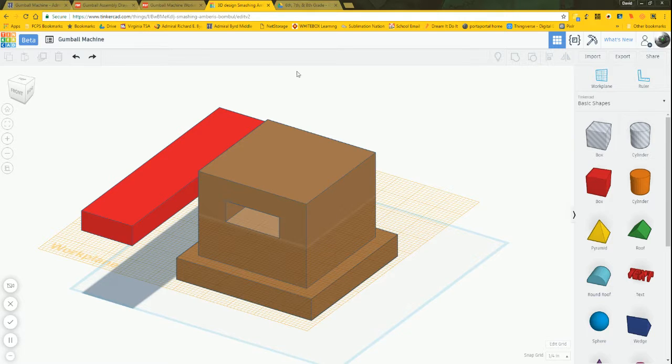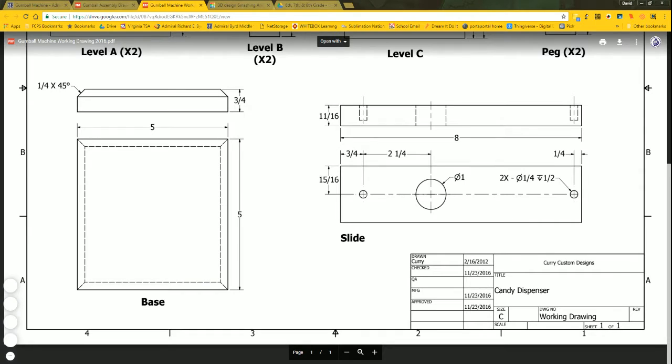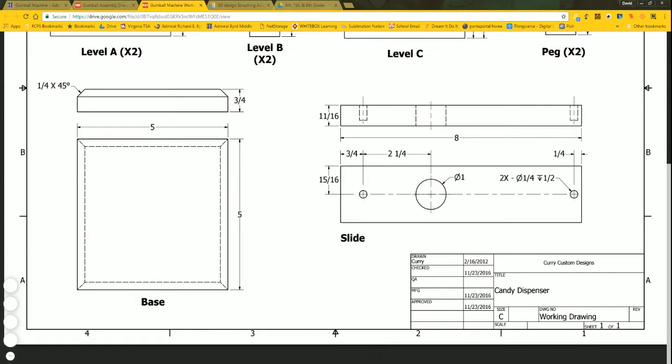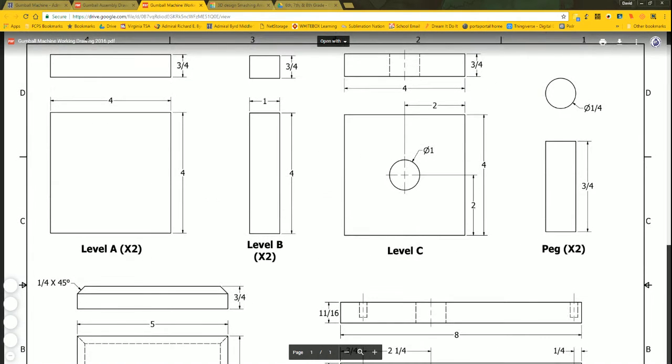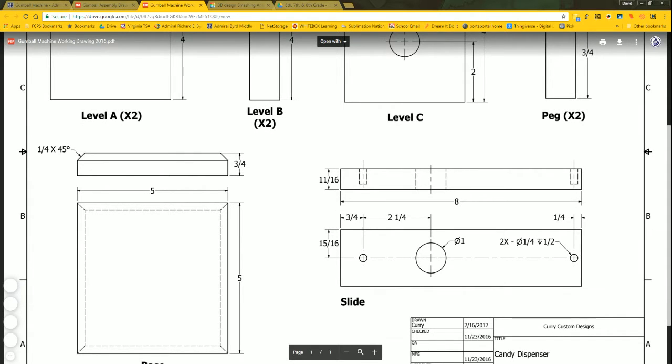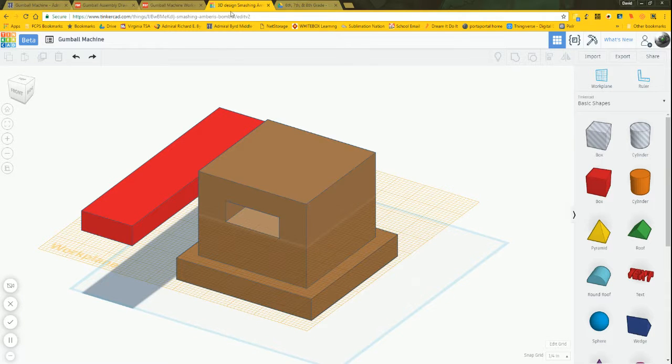We're going to have, technically there's 3 holes. We're only going to put 1 hole in here. And the reason being, the 2 1/4-inch holes are blind holes. They do not go the whole way through the part. I don't have to put that in for what we're doing here. We're just making a 3D model. It doesn't need to have that. I need the through hole though, because it's exactly that. It goes the whole way through the part. Let's put in the through hole, and then we'll come back and deal with the pegs, which, here's the actual pegs which fit into the holes. It'll be quick and simple. We'll come back to that.